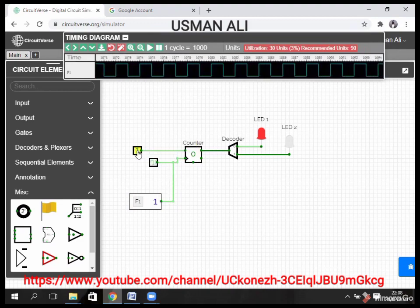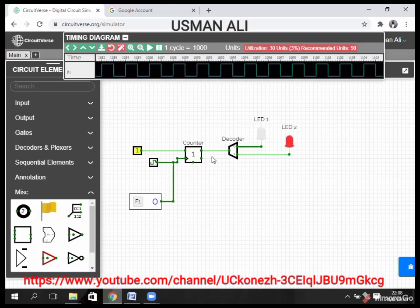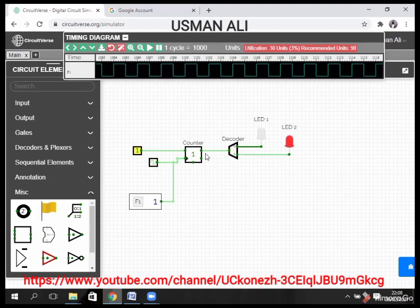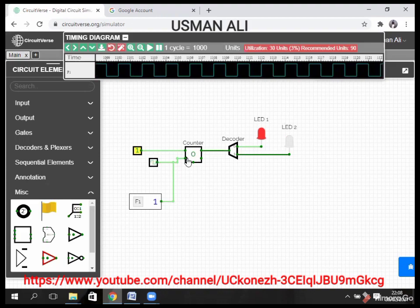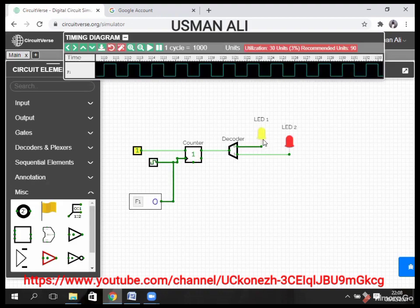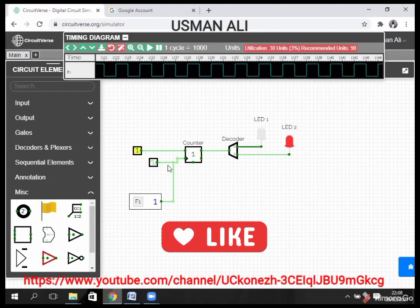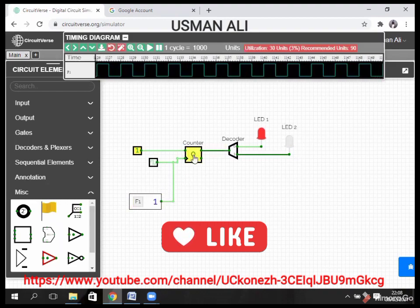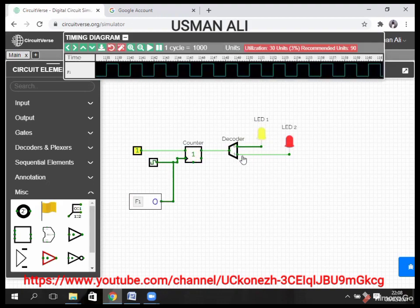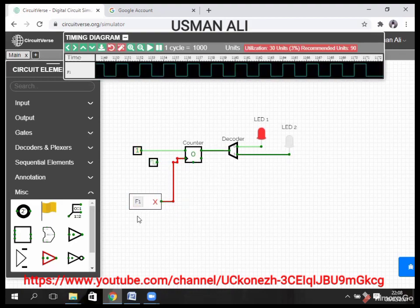Now we increase the max value to 1. Now it means it changes its number to first and second, 0 and 1. When the clock goes high, it goes to the first point, first 0. For that point, the decoder decodes it and places it here and points the signal to the first LED, then decodes the second point to here. Now you see when our clock changes its point, the counter also changes point. Then the decoder decodes it, and our first LED lights on, then our second LED lights on. Now we disconnect our clock here.